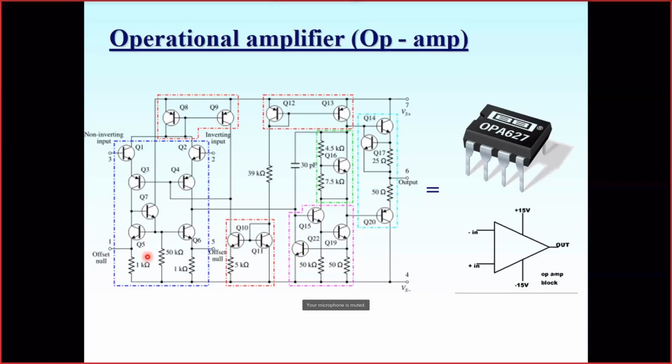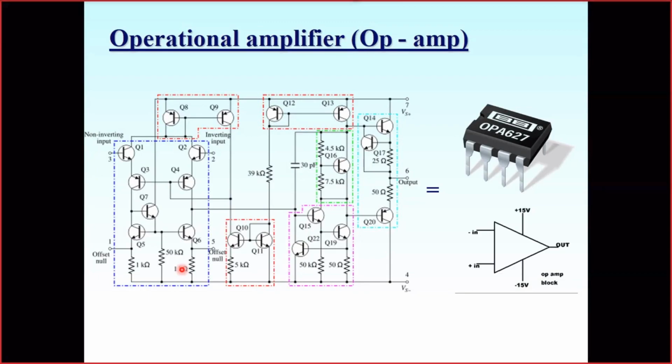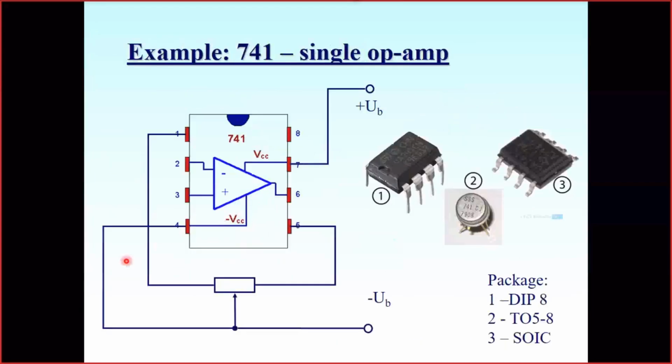These resistors are polished with a laser beam to control the thickness and to adjust the value of the resistance, to have as good an operational amplifier as possible. But in general, we may do it by connecting a potentiometer between the first and fifth legs of the 741, and attaching the slider of the potentiometer to the negative voltage supply pole.